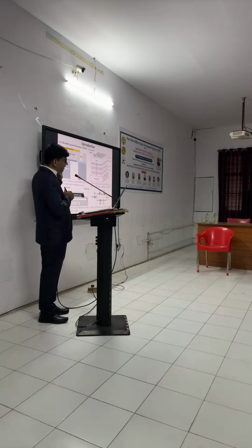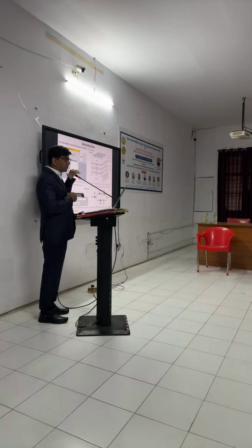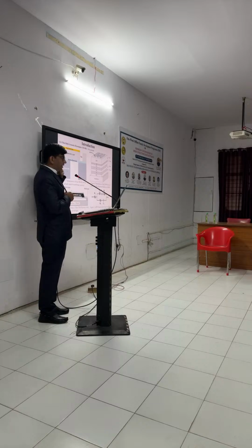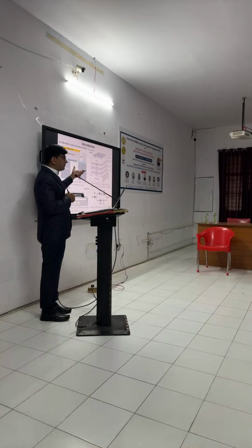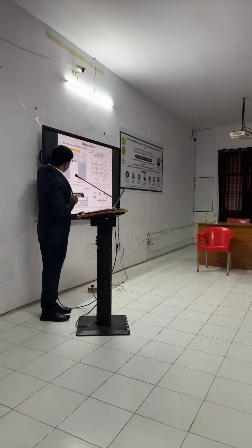So what we have here, we have first a silicon substrate, over which we will deposit an oxide layer, and then we have a bottom electrode, then a piezoelectric layer, and then a top electrode. Now, all these three layers we can deposit with the help of photolithography and patterning. In this case, the thickness is in our hand. What kind of thickness we want, we can control with the help of the deposition process for the piezoelectric layer.